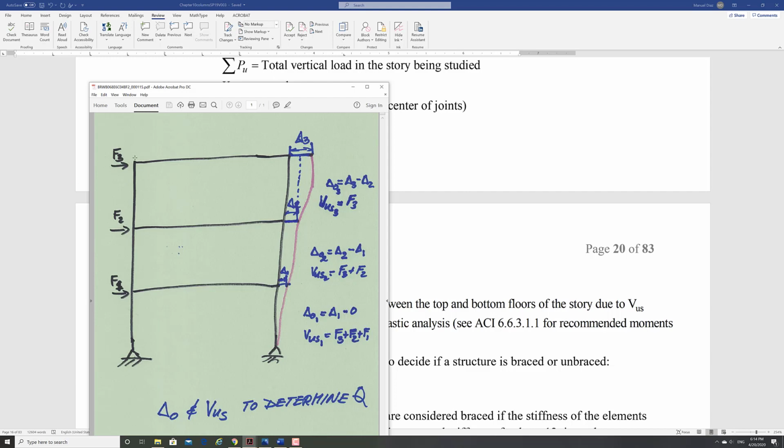So you get that one. What is your shear for story number 3? Well, you make a cut here, right, before it, and your reaction has to match this force. So the reactions in your columns have to add to this number. That is your shear at that story. You look for the second story, you make a cut right before it. Again, the reactions on these columns have to add to these two forces. So now you got your shear on that story. Then here, you find your horizontal reactions. Those have to be equal to these three forces. So you have your shear on the first story.